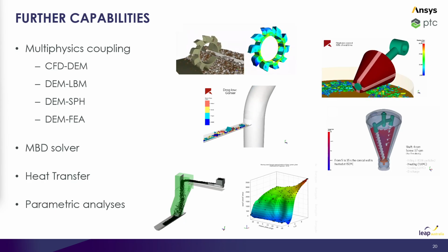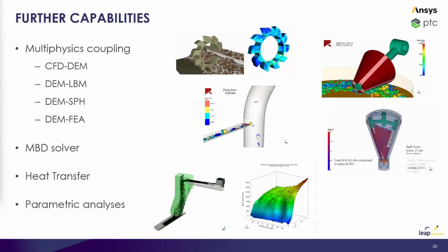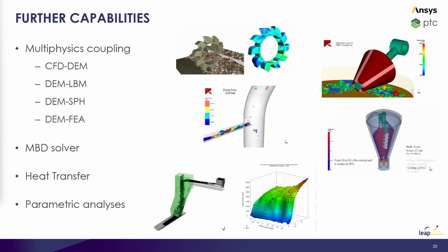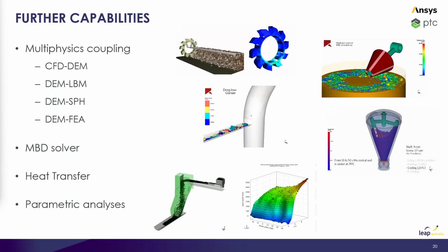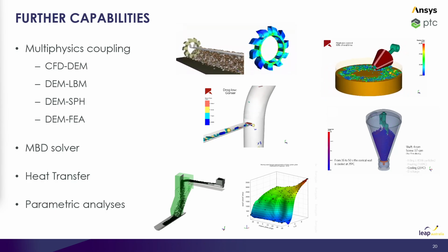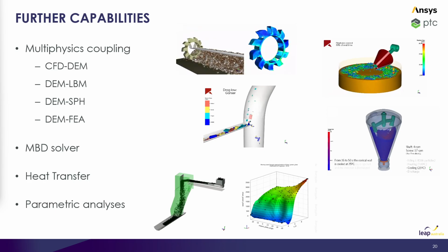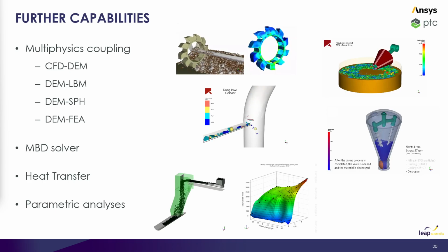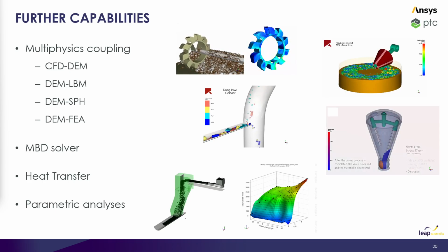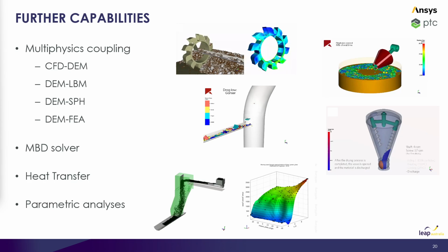So we can gain an understanding, as we can see in this graph at the bottom of the screen, of what the system response will be if we vary certain parameters. If we take, for example, varying the impact plate angle and the feed conveyor belt speed, how does the shear power or shear intensity change on the deflector plate itself? And we can create a response surface to describe this system.